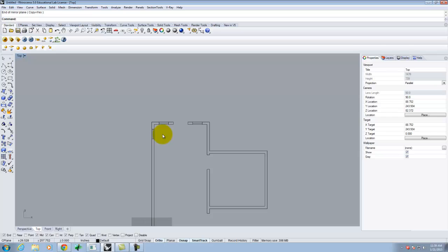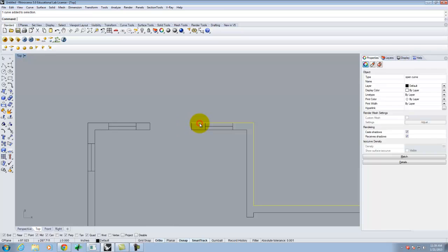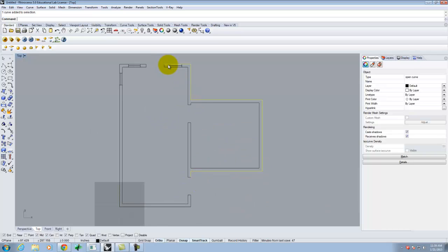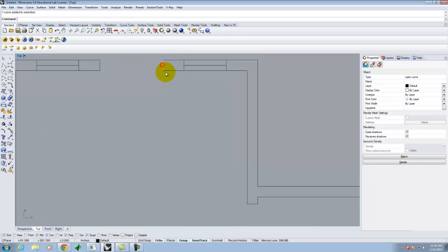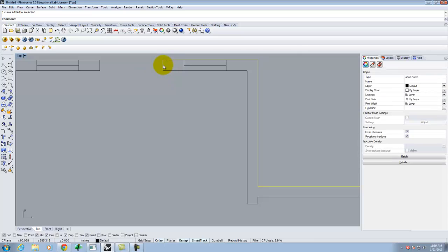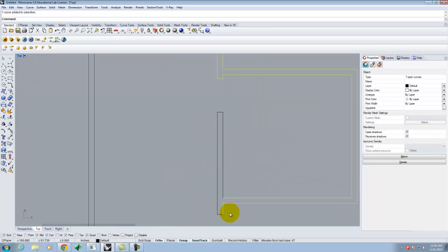Mirror. The last thing that can be helpful down the road, especially when you're building 3D objects, is to actually join curves together. And so you can see that I have this curve here selected, but then if I get to this corner, it's a separate curve, and then I have this piece which is separate. If I select these together, if I hold down Shift, I can click on them. There. And we can go around this.